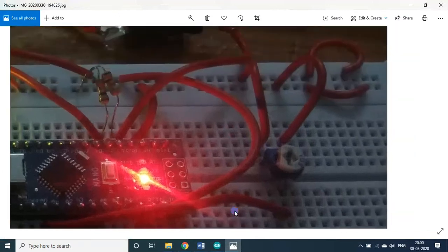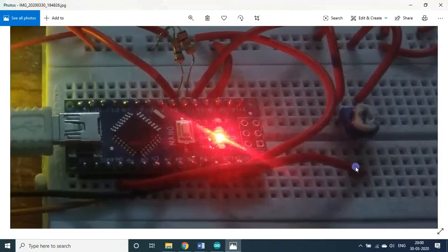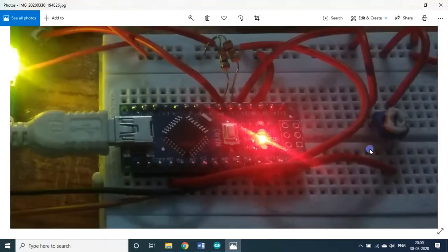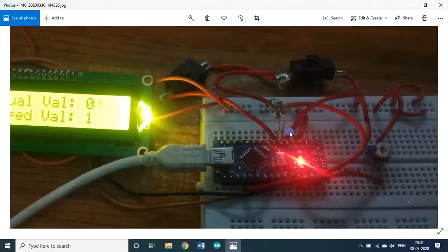The image is not that good, so I connected this one, this is the variable resistor. The midpoint, you see this wire is connected with this A0. So this is A0, this is A0, they are connected here, midpoint. This left end is connected to 0 volt, this right end is connected to 5 volt. Very simple. The IDC connection.